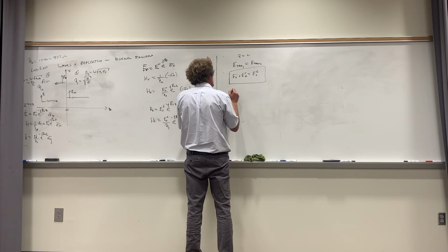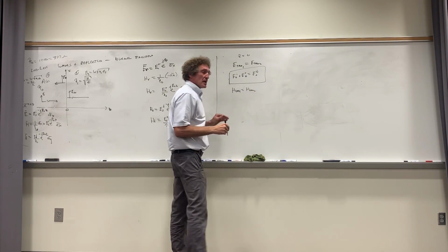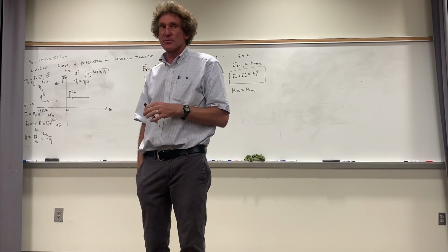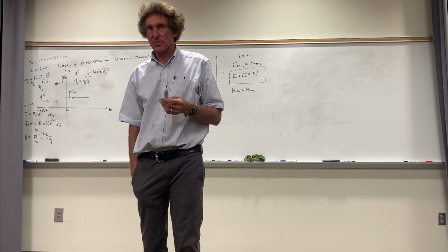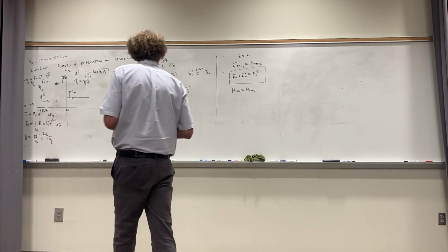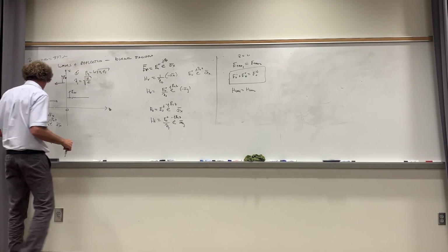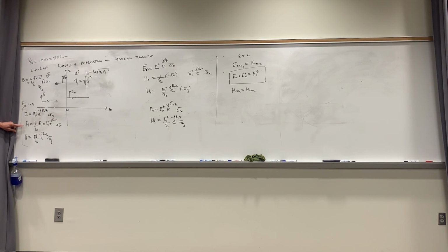Now the second equation is H tan 1 is equal to H tan 2. Do you remember that from EMAG 1? H tan 1 is H tan 2. Now that's assuming there's no surface current. There is none here. So when we do that, well, what's your tangent field in region 1? Take a look at it. In region 1, we have this, right? E naught incident over eta naught, right?